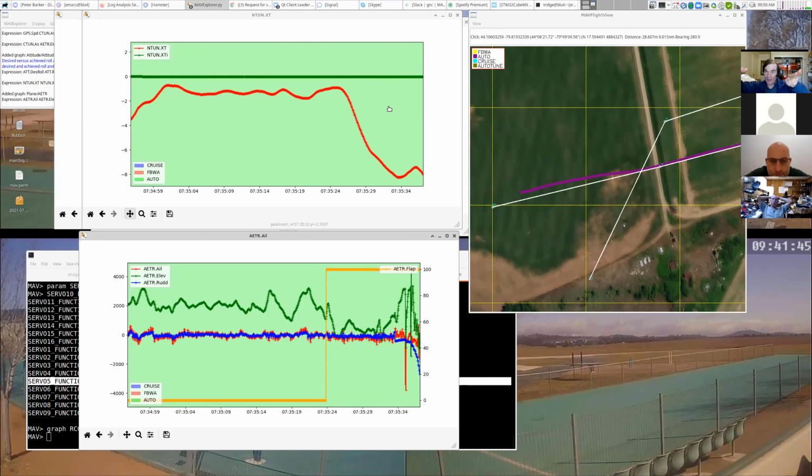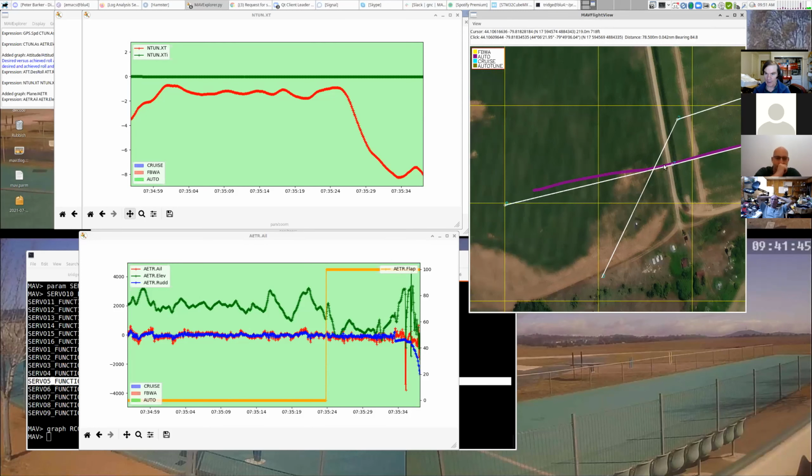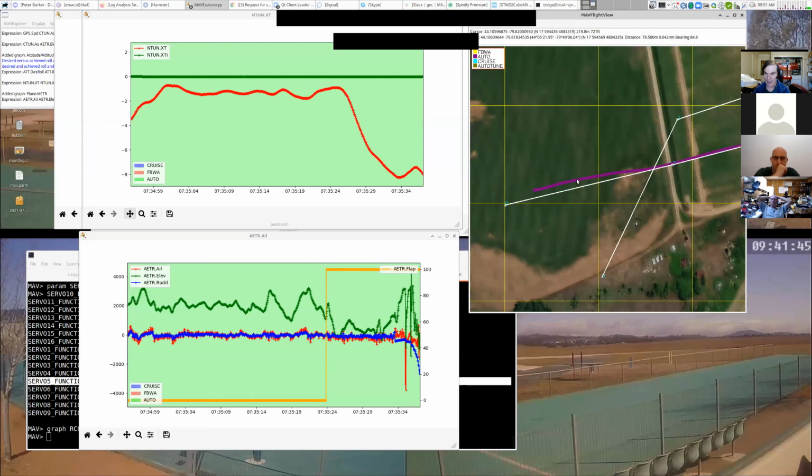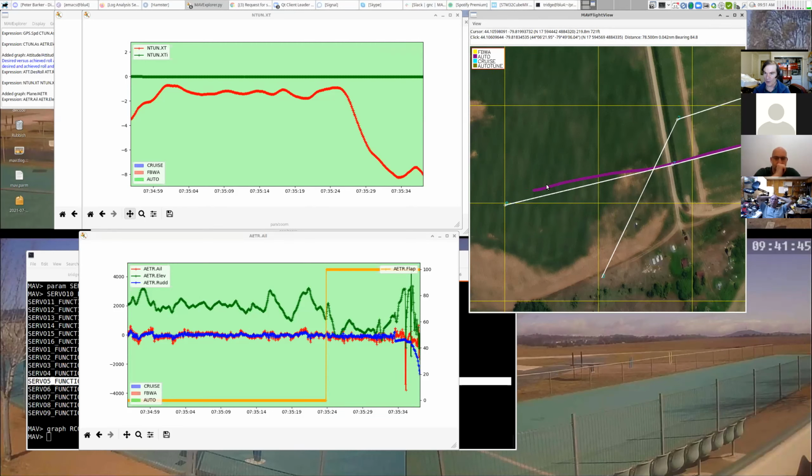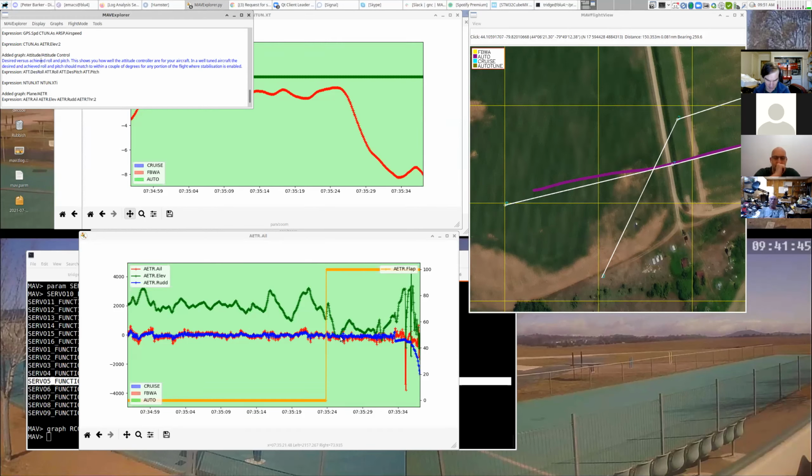The flaps are offset a little bit, because what appears to be happening is that it's running basically the same algorithm here as it's flying in this part, but it's deviating a lot more, and the difference appears to be his flaps. So I would be suspicious that he's got an issue with his flap servos. Now, it's not a very long distance here. He's flying, what sort of speed? I've just measured a distance of about 150 meters, so that's coming in over something like 10 seconds.